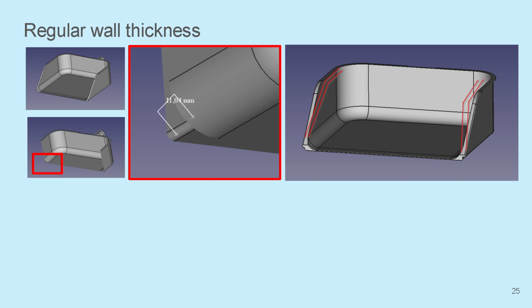Why have I mentioned cooling time? For a plastic part, it is good to know about shrinkage and warpage. Shrinkage is different for each material kind. For example, for PC/ABS, it is about 0.6%. If the wall thickness is regular, shrinkage is also regular. And of course, this causes warpage to be also regular, or it can be said warpage in each direction is the same. This matches very well for a plate.